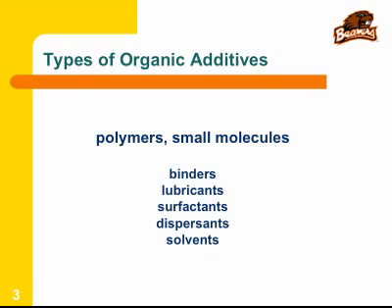Right? Lubricants. So in some cases, you had to push the powder into a die. There is a lot of friction. Right? If it's ceramic particles, they're very hard and abrasive, and a lot of the energy that is used for compaction is dissipated by powder-powder friction.